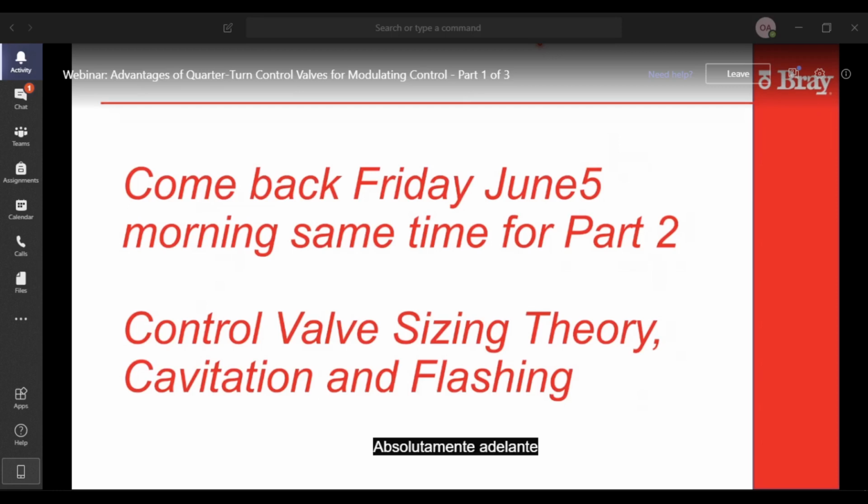Absolutely. Go ahead, Ralph. Well, if it's a gas or a liquid, the characteristics of the liquid or the gas play heavily into what you're selecting as a control mechanism. So yeah, there's abrasion, temperature, solids, what type of solids are going through it. Compressibility. Yeah. Well, on gases, you'll need to compensate the outlet for the volume increase.